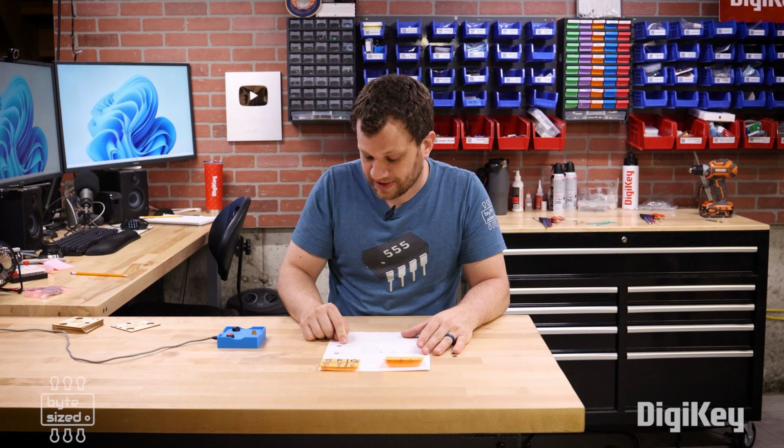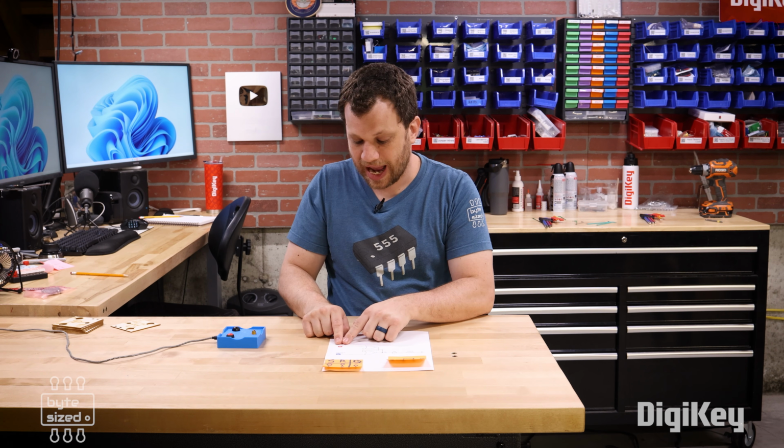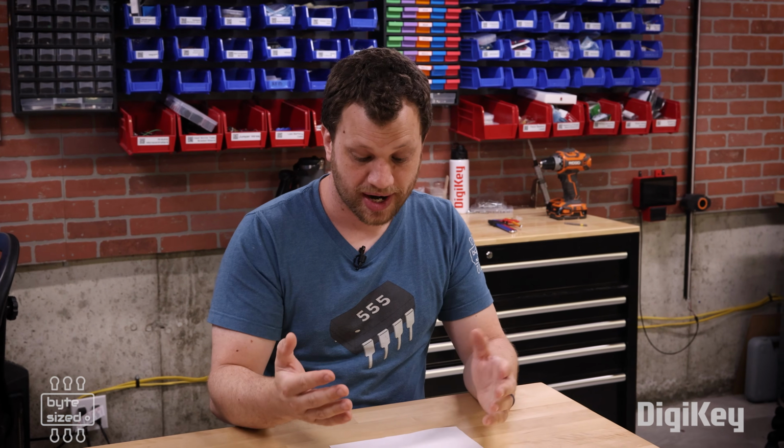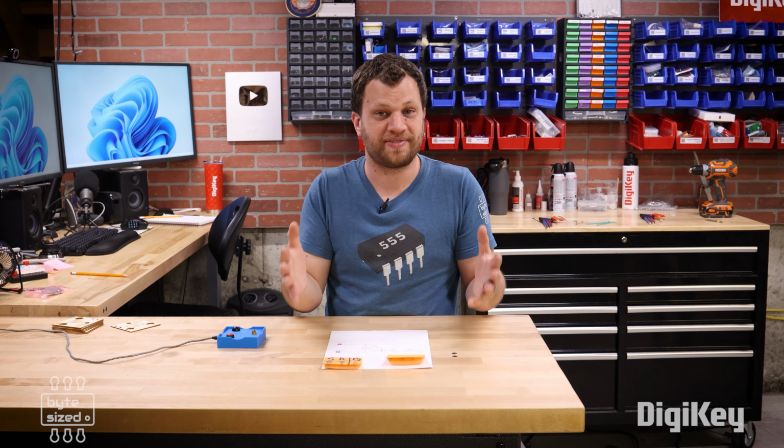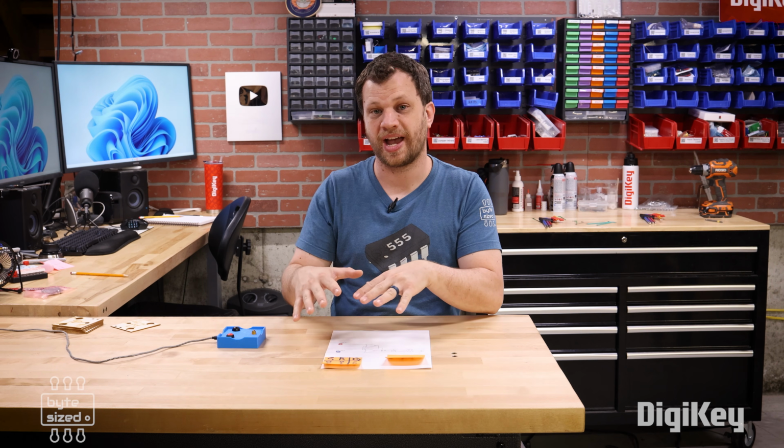However, when we activate the set input, the output gets latched high. It doesn't matter what happens to the set input, the output will remain latched high. Likewise, we can activate the reset input and the output goes low. No matter what happens to the reset input, our output remains latched low. The fourth state is actually an invalid state. It's when both the set and reset inputs are activated at the same time. It causes a race condition and the logic breaks down. So we need to avoid that input state.